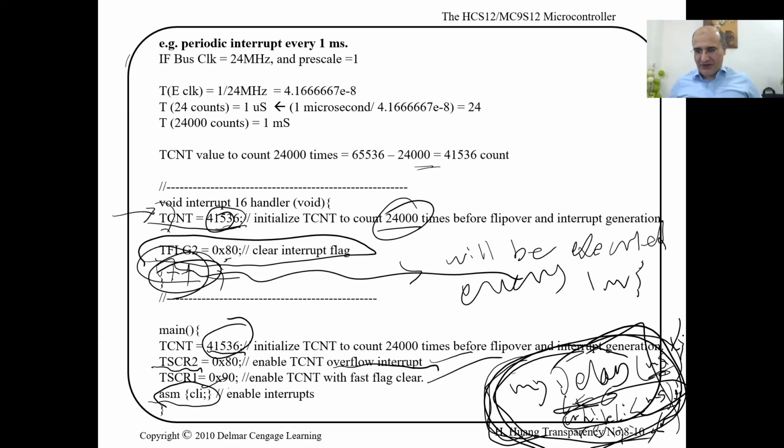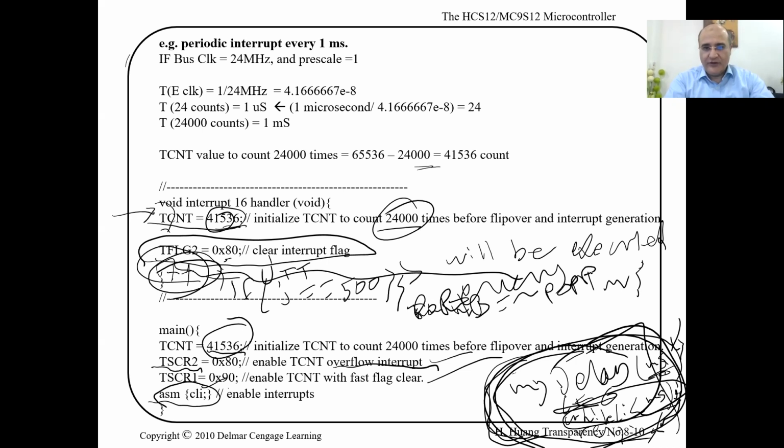So this delay will cause your program to get stuck here for 100 milliseconds, or 1,000 milliseconds, or whatever. We did an example, I remember, but using the real-time interrupt. If you want to enable something every amount of time, for example blink the LEDs every 500 milliseconds on, 500 milliseconds off, you can increment j, j++, and say if j equals 500 milliseconds, turn on LEDs, or port B equals the complement of port B. Then reset j back to 0.